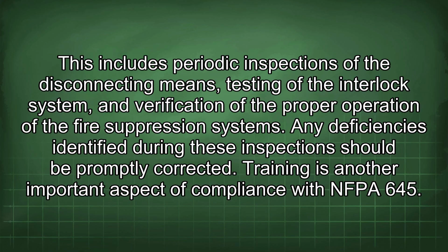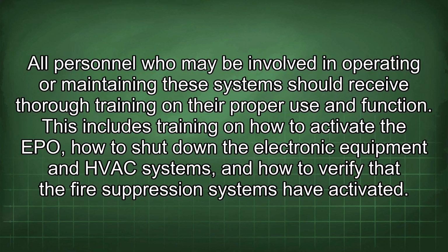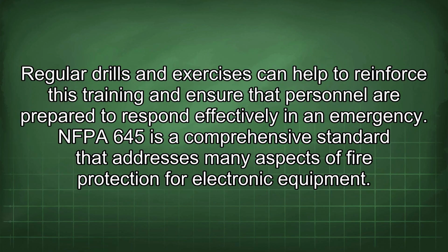Training is another important aspect of compliance with NFPA 645. All personnel who may be involved in operating or maintaining these systems should receive thorough training on their proper use and function. This includes training on how to activate the EPO, how to shut down the electronic equipment and HVAC systems, and how to verify that the fire suppression systems have activated. Regular drills and exercises can help to reinforce this training and ensure that personnel are prepared to respond effectively in an emergency.